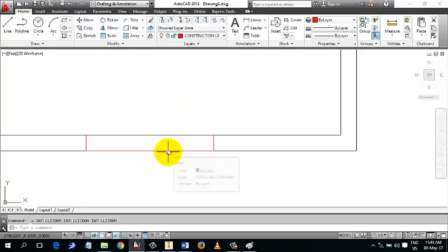You see, you may not take yourself through all this trouble. Since you have demarcated between 1,200 and I use the middle point here to draw a line 600 this direction, 600 the other direction, and I draw it up to create the demarcation. You can use trim. Am I right? Trim will work, or you use break to cut the window area.